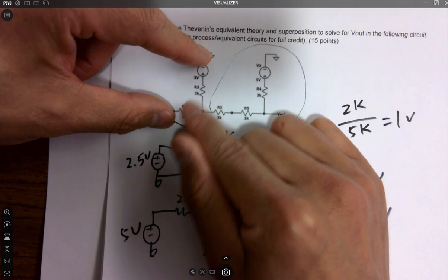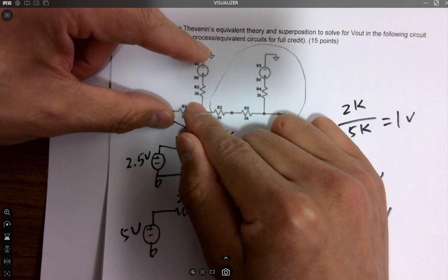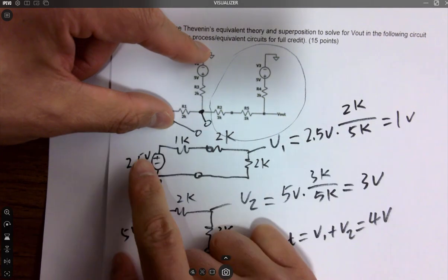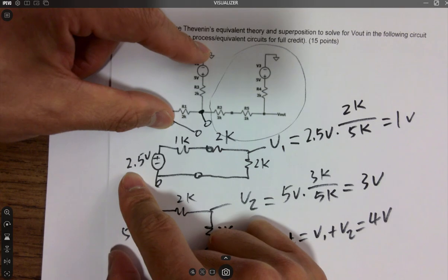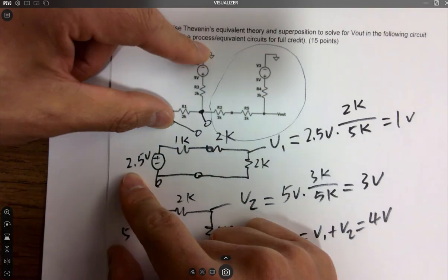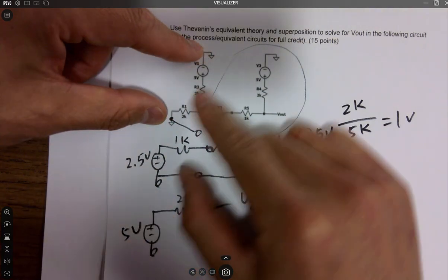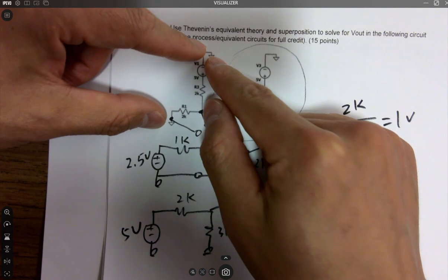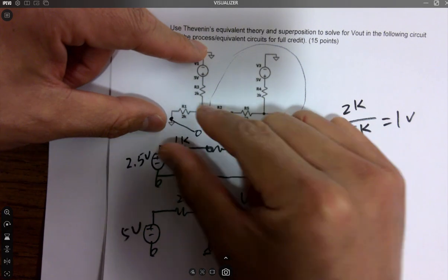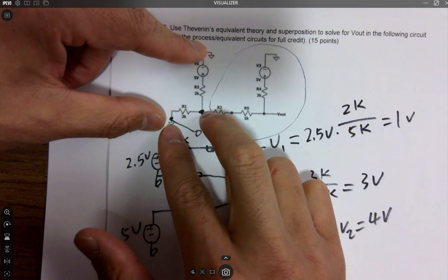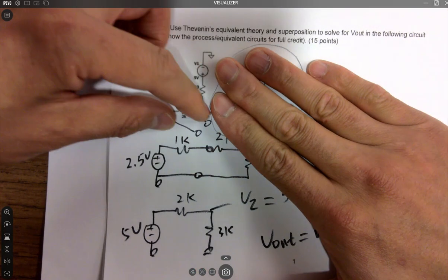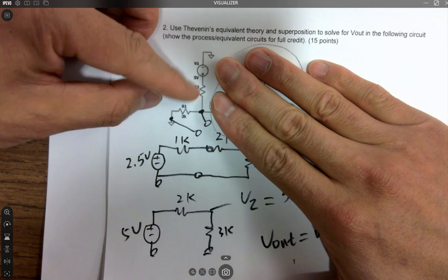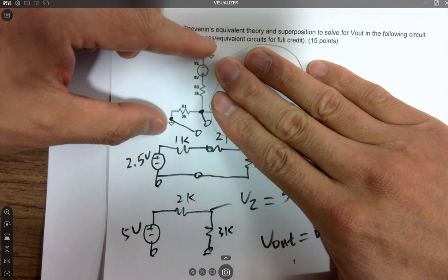So that's RTH. And then you just multiply the Vin times R2 over R1 plus R2, right? So then 1/2 times 5 volts, right? Which is how you got the 2.5 volts. It's a VTH. VTH is you calculate. So VTH is when you remove the load from the output network, right? So the voltage that appears here will be VTH. And you can see this is the voltage divider, 2Ks, 2.5 volts for VTH.